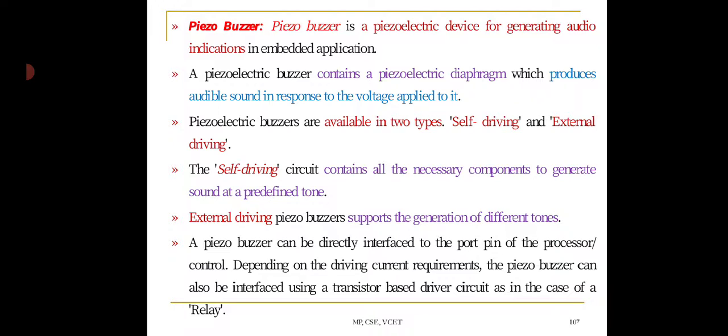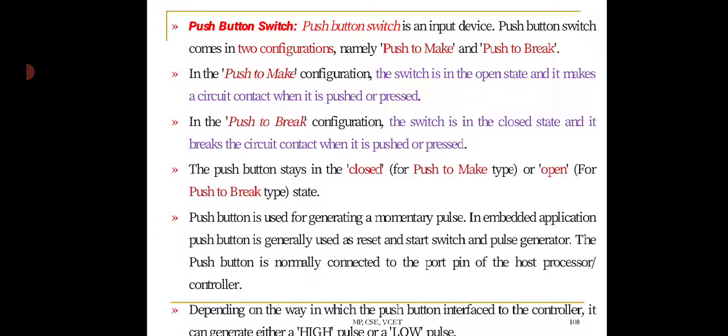A piezo buzzer can be directly interfaced to the port pin of the processor or controller. Depending on the driving current requirement, the piezo buzzer can be interfaced using a transistor-based driver circuit, as shown in the case of relay.